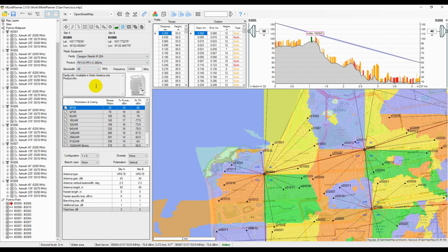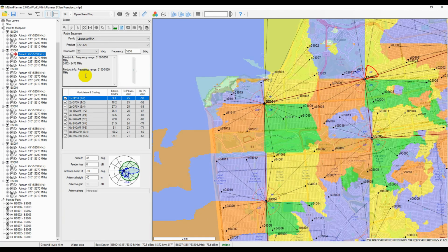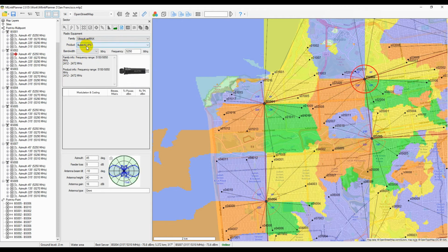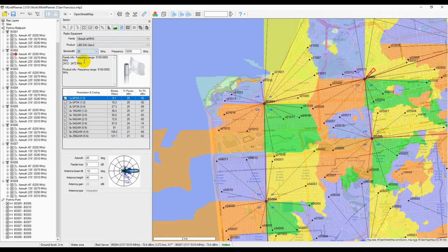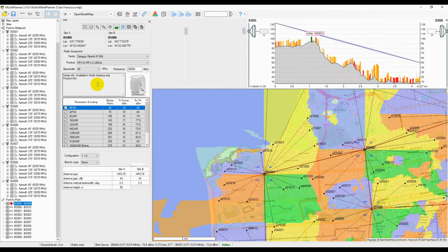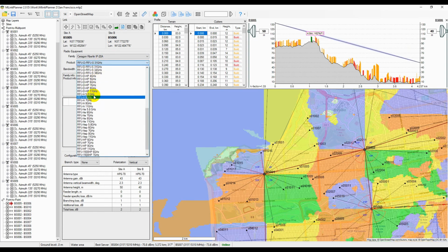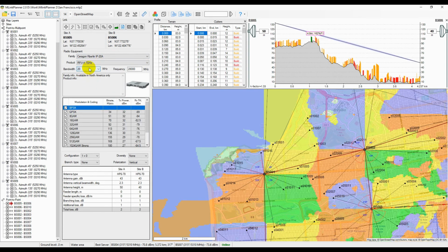The common parameters for this family are modulation and coding parameters, as well as a set of bandwidths. An example for point-to-multipoint equipment is the popular AirMax family by Ubiquiti Networks, which includes many products of base stations and subscriber stations that are compatible with one another. An example family for point-to-point equipment is FibeAir IP20N by Ceragon, which includes a set of external placement of different radio frequency units, known as RFUs, or even different frequency bands.